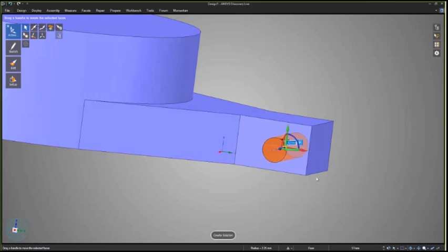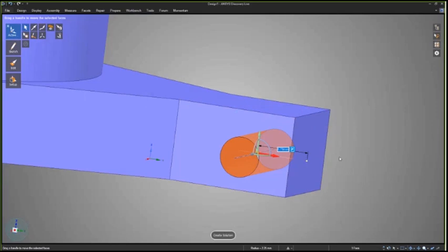And what's nice is, we saw the pull tool has dimensions, so does move. Here it's telling me how much I'm moving it. So if I want to move it 1 millimeter, that's good. I can also set up dimensions exactly to something else like this face here. So that should be exactly 5 millimeters, easy to do.